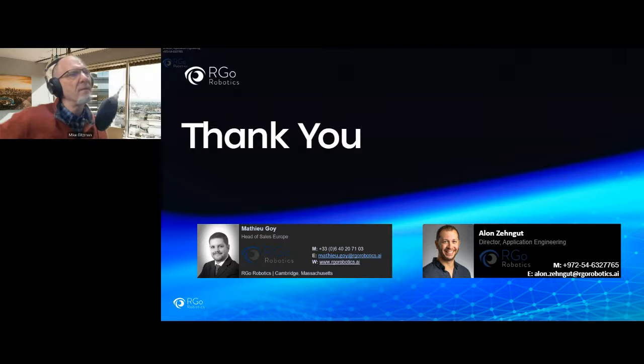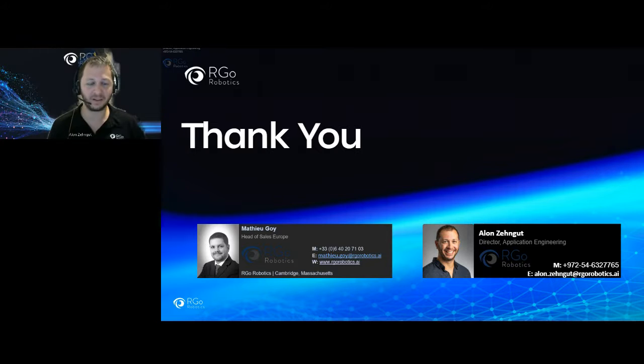Right. So maybe just to clear this out, for localization, accurate 3D localization, we don't use any 3D depth, any depth camera at all. We can use a single fisheye monocular camera, and this is the one we use for localization. Then, of course, for obstacle detection, we use depth cameras or time of flight or different technologies, and the number of them will depend on the application and the field of view coverage you will need to achieve with your machine.